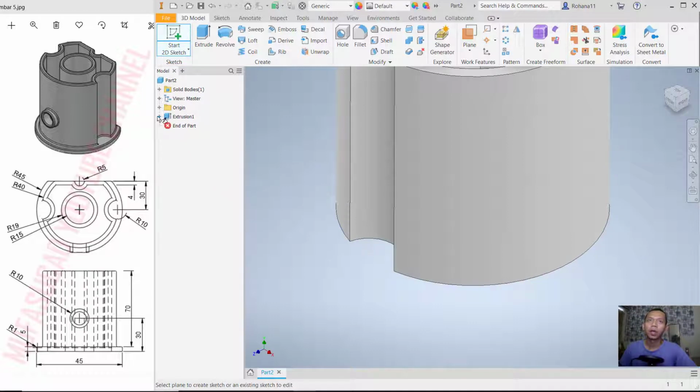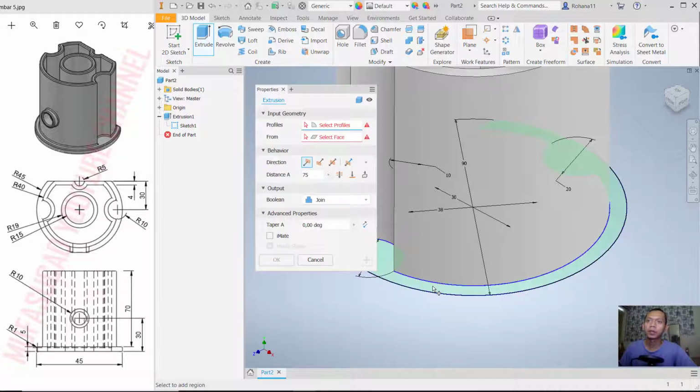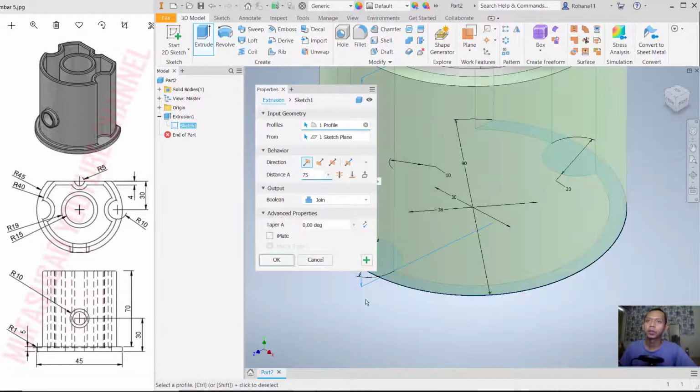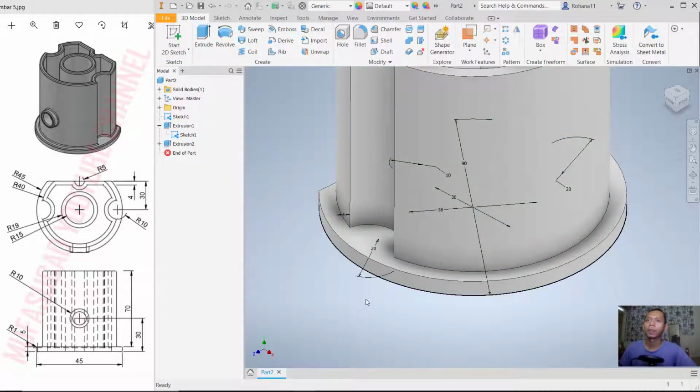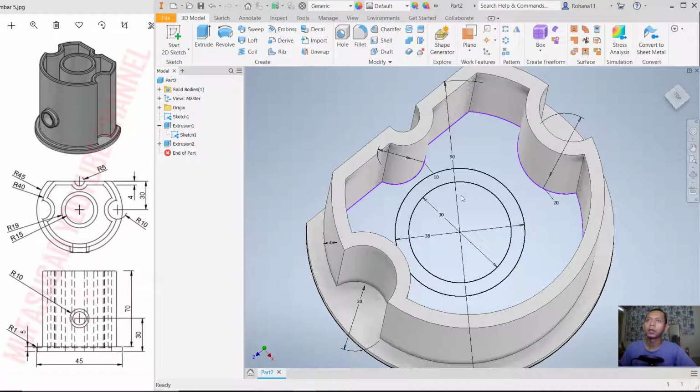You can activate sketch 1, right click and we can set visibility to on, so it will appear for the sketch models. You need to extrude again at this face. You can extrude 5. You can press enter. Next, use the orbit tool to see the inside here.